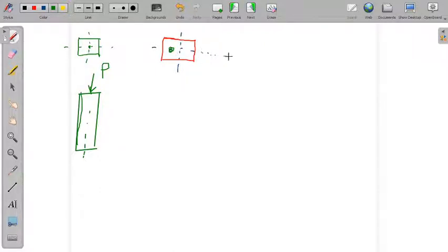Even it can be outside also, but it is on any one of the axes. So if I want to find out the moment, say the load is in this particular location, if this is the eccentricity e, and this is P, then the moment will be P into e. So this is called the second category, that is uniaxially loaded column.